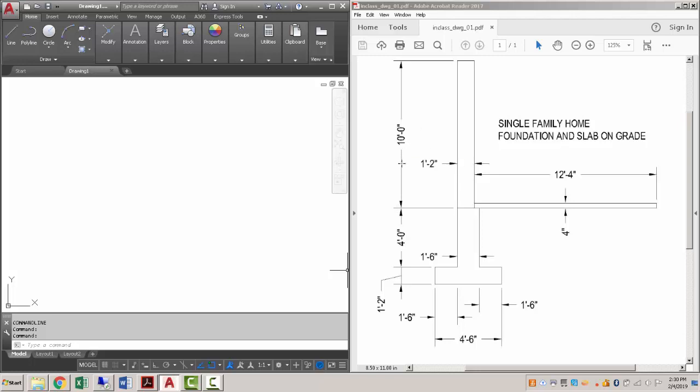So these particular dimensions are set up to have arrows for the arrow type. Some of them can have ticks. We'll get into that a little bit later on in the class. Here's another dimension line that doesn't actually have extensions. It's just measuring the dimension of the exterior wall, and you can see the dimensions given off here to the left. This is an example of a dimension that only has one extension line because the other mimics the actual object line, so you don't show it. Again, this one's just measuring a thickness, and then some other examples down here.